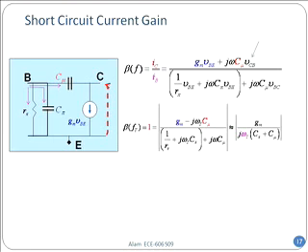So then, this is my gain at any frequency. As you change your omega, this ratio will keep changing, and as a result, my gain will be changing. Now, at what point does the gain go from 100 to roll off and then become 1? That whatever input signal I put, I don't get any amplification. So that is the point when I'll call that frequency f sub t, and that must be equal to 1, right, by definition. So I want to know at what f sub t will my gain become 1.